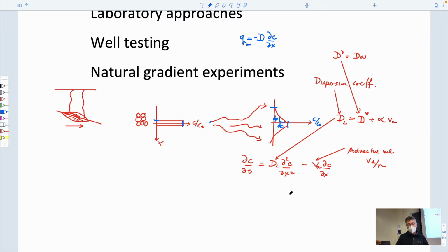And so we recognize that with the diffusion equation, and this is accumulation. And accumulation has to equal mass in minus mass out. That's all it is. And last Tuesday, a week ago, we'd have made the point that this mass in minus mass out can come from two sources. It can come from advection, water carried with ink in it, physically carried into the element and then carried out, as in a beaker.